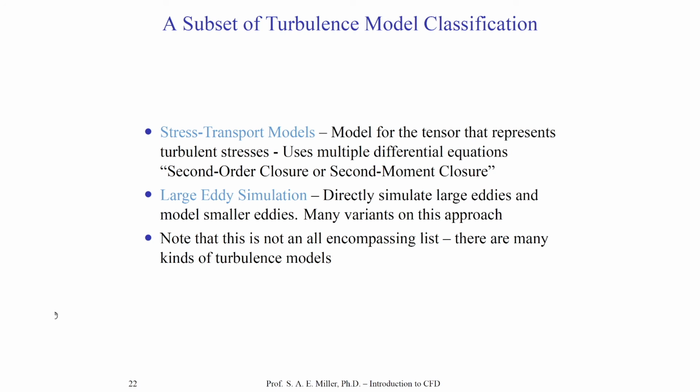Finally, we'll spend a whole class on direct numerical simulation, and what is becoming very popular today in research and industry, which is a little bit different, is called large eddy simulation. This is the idea that we're going to directly model the largest scales of turbulence in the flow with, say, the Navier-Stokes equations. And all the smaller scales, because they have some universal behavior, according to Kolmogorov and colleagues in the School of Turbulence, we will model them.